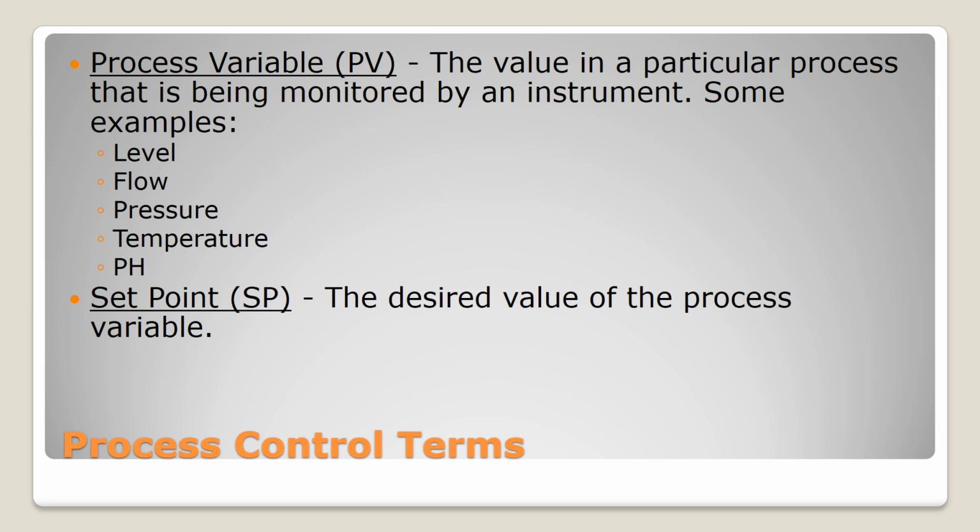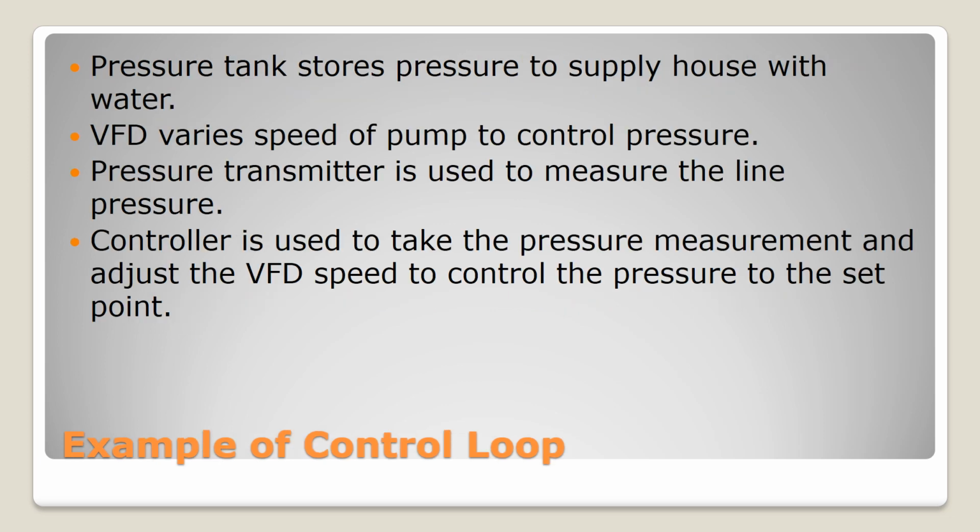And then we're going to have a set point, which is that desired level, the desired flow, the desired pressure, the desired temperature, or the desired pH, and have a control system that will help us maintain that set point.